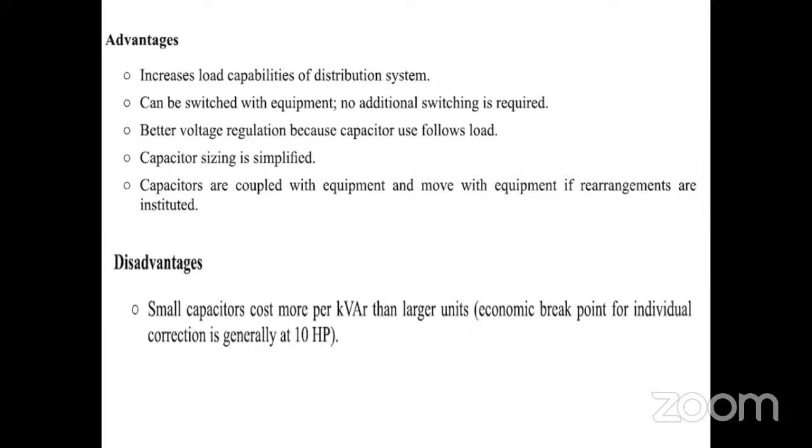That's the only economical disadvantage. It should be noted that the rating of the capacitor should not be greater than the no load magnetizing kVAR of the motor. One important point, sir.